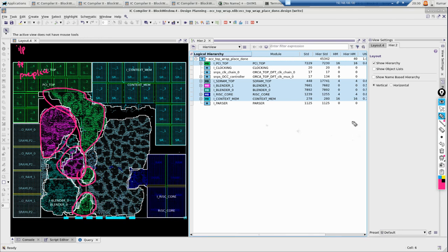Ideally speaking, I know it seems like there are some IO ports that are interacting with the macros that are placed over here. You know what I would do in this scenario? Pull these macros here. Probably this would reduce this logic spreading. So these are all the kind of QA checks that we do to make sure you are having the optimum design, in terms of cell count, power, performance, and area and everything. So, placement.